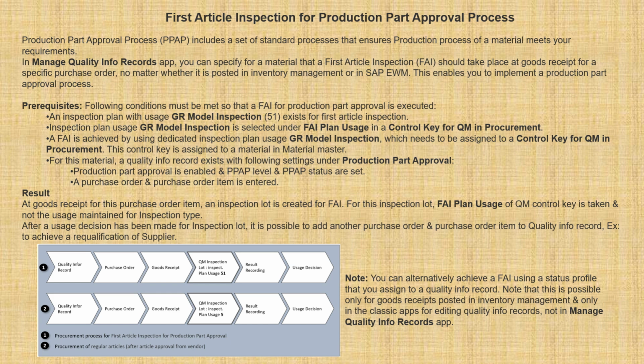in bulk. Before that they don't start, because if they find any defect, then in all the remaining material you will get that same defect, right? So that's why on the very first piece only, you are doing the inspection with very strict rules. And you will be doing the setting in the system that the first piece should be inspected.